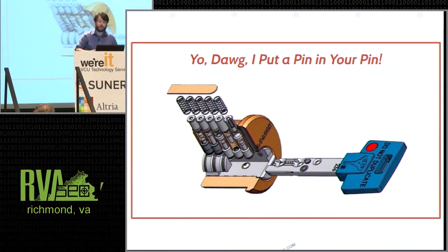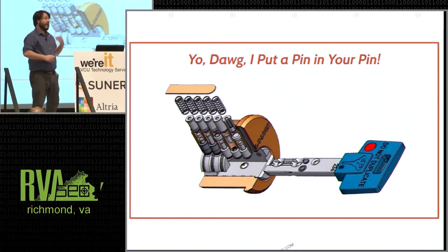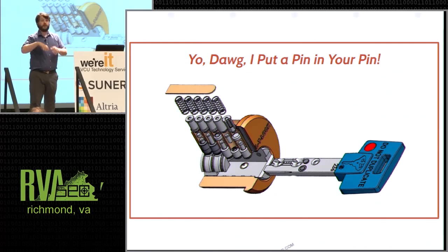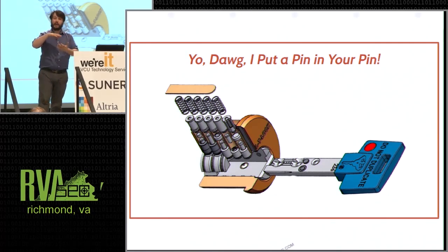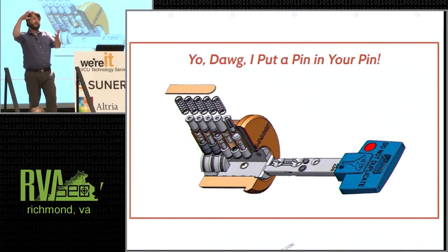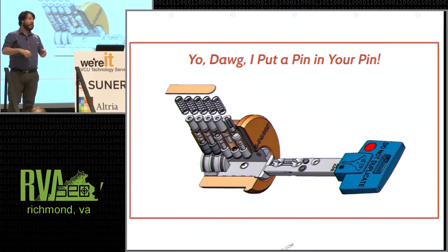When Multilock rolls in with their pin-in-pin system, this becomes incredibly difficult. That inner pin is so small, and the way that all of the rakes work is that it will lift both outer and inner pin to the same height. But the outer and the inner pins can actually be at different heights. They accomplish this in the key by milling in two circles, little concentric crater marks into the key. One will lift the interior pin, one will lift the exterior pin, lifting them both up to different heights.